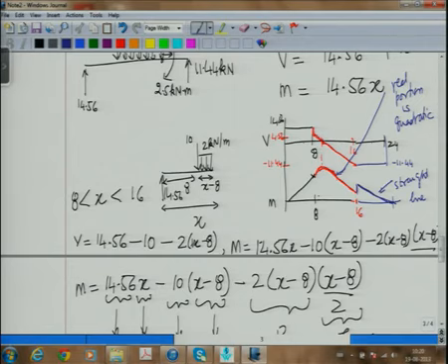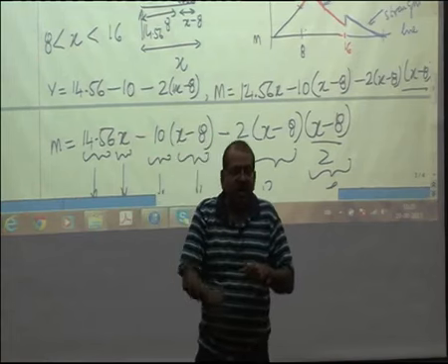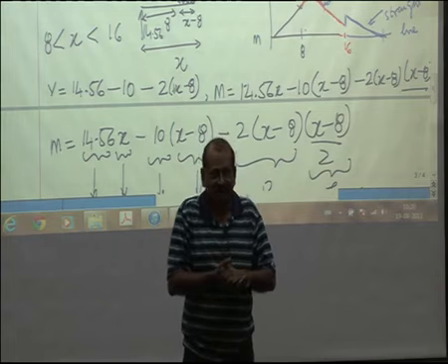Okay, so this is how we draw the shear force and bending moment diagrams. This example illustrated 2 or 3 points. One thing I told you was how to take care of forces acting at an offset. If the part is welded, then you will also get a moment. If there is a joint only, you will not get a moment, you will only get reactions.